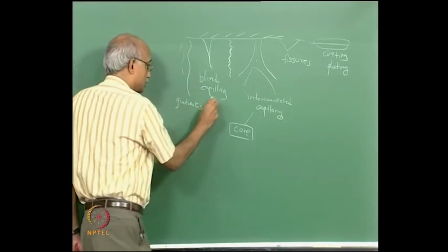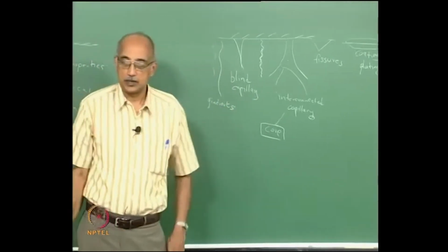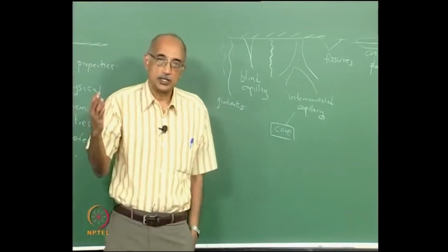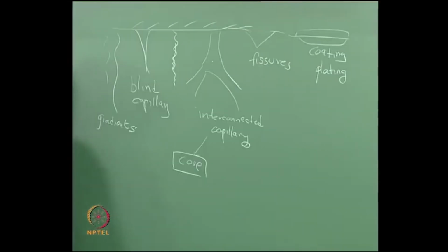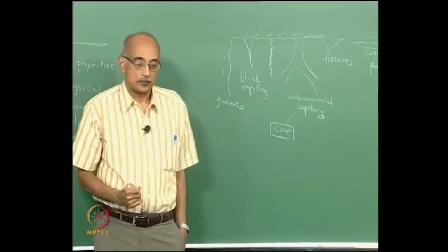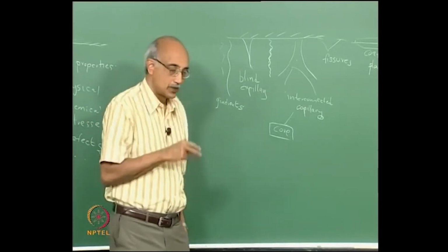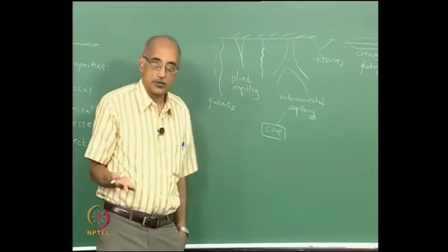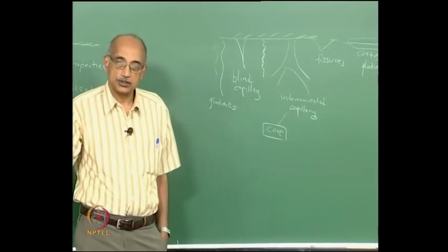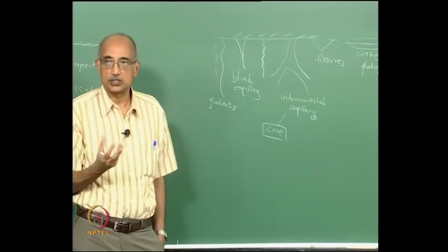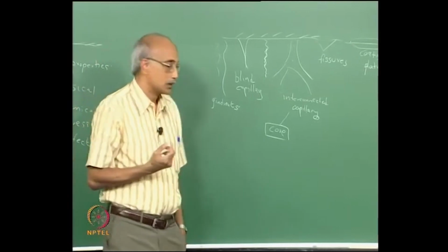So if you are using a SEM EDX type of analyzer, you can actually see a gradient in the composition of the material. If you are doing a measurement, for example, if you are using an XRD for your characterization, you will see a gradient in the crystalline structure of the material.